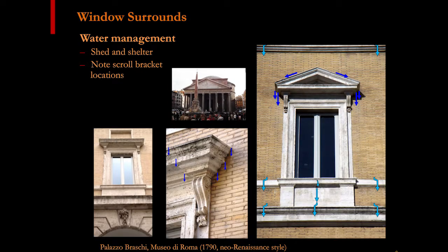So if you think about water that's hitting this facade, what's hitting here is in part absorbed by the brick and is in part cascading down over the surface. The glass is totally impervious and non-absorptive, so everything that hits this window is being funneled to this point right here. And that's where you have a very, very thin wall underneath.